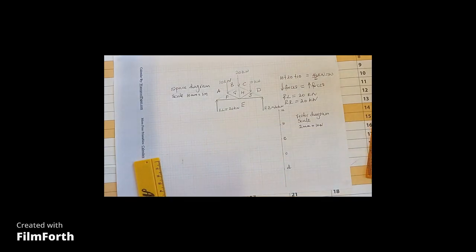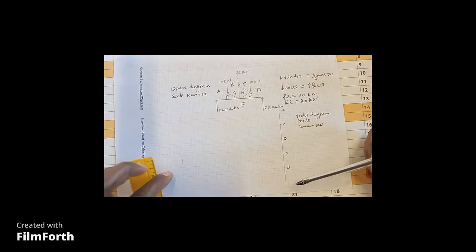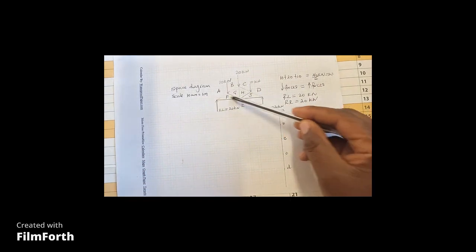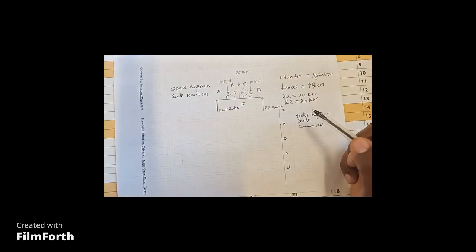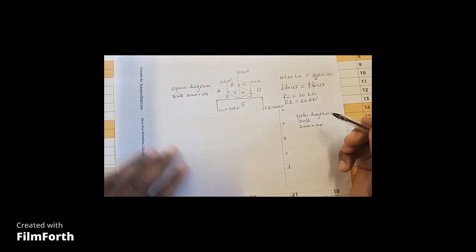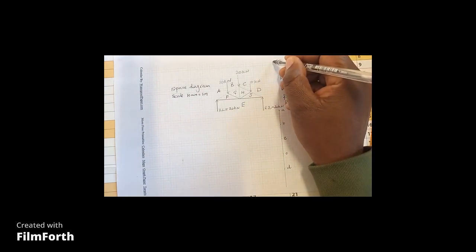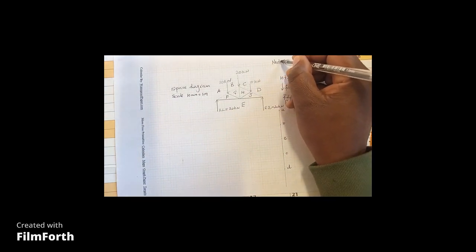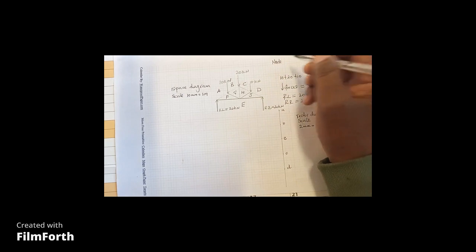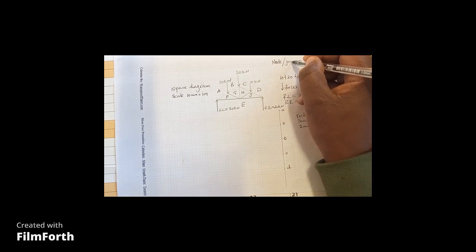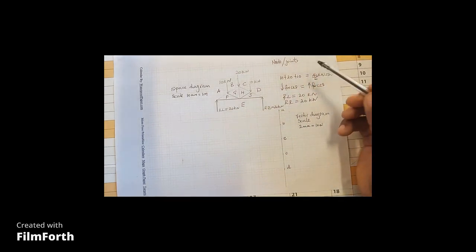So we all have now the external forces or the downward forces, including the reactions, all represented here on this vertical line. Now we need to draw up the members. For us to do this, we want to show all these members, right? For us to do this, we are going to work with what we call joints or nodes. So I'll just write here, it's a node, that's N-O-D-E, or we can simply say joints. I'll explain what we mean regarding this.